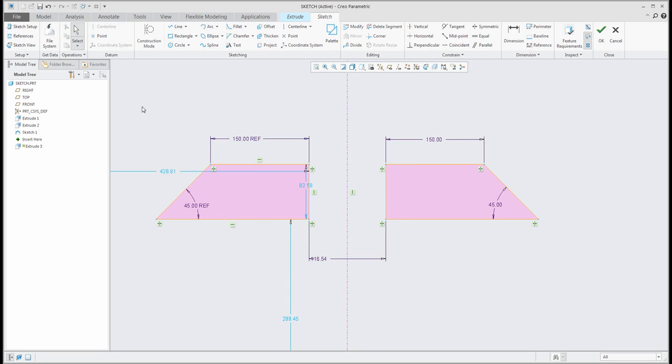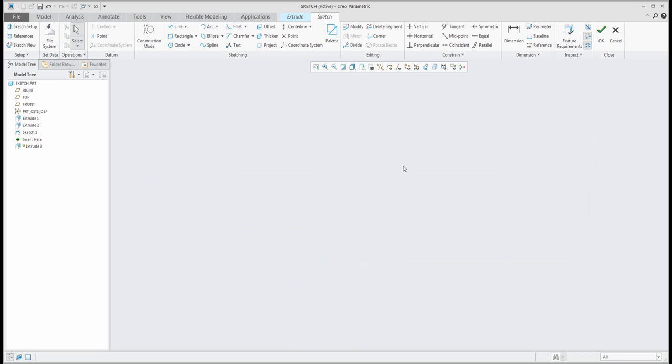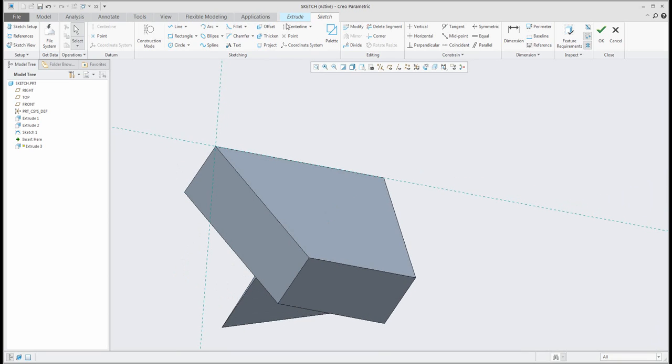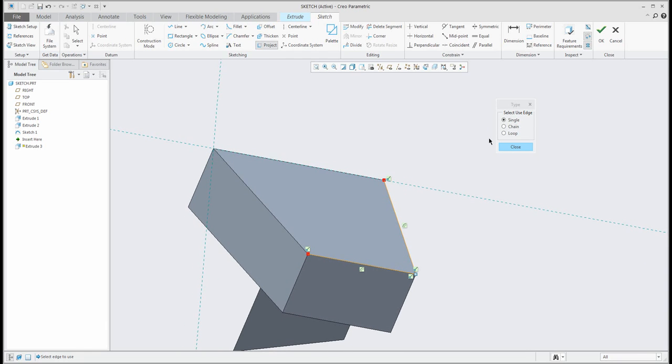I'd like to continue on that sketch. I don't want to create a lot of new sketches here, so I'd like to continue. And for example, I'd like to focus on the feature what is defined here, that we would like to create a projection. So if we need to project some existing edges or lines, you can select the function create a project feature, and the system asks you if we would like to create a single edge. So I'd like to select that edge, and the system will automatically project this edge. Yeah. If I select another edge, the system will add the projection here.